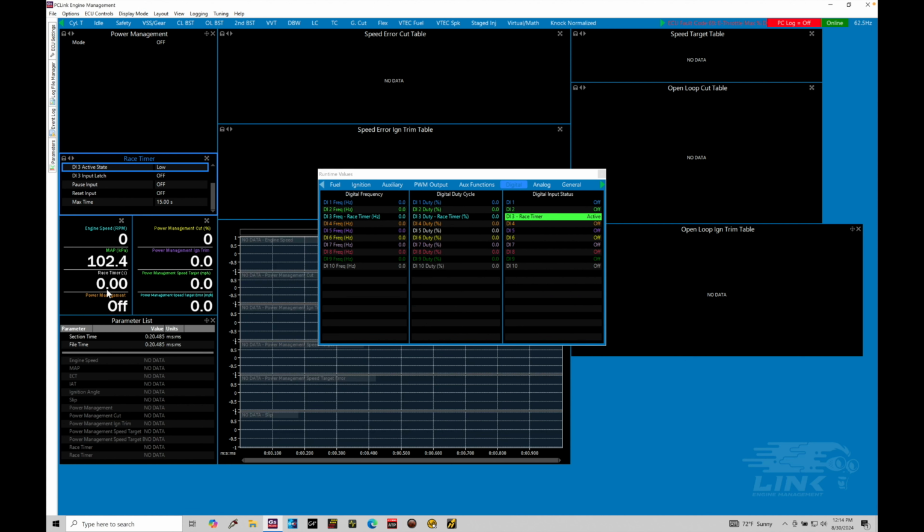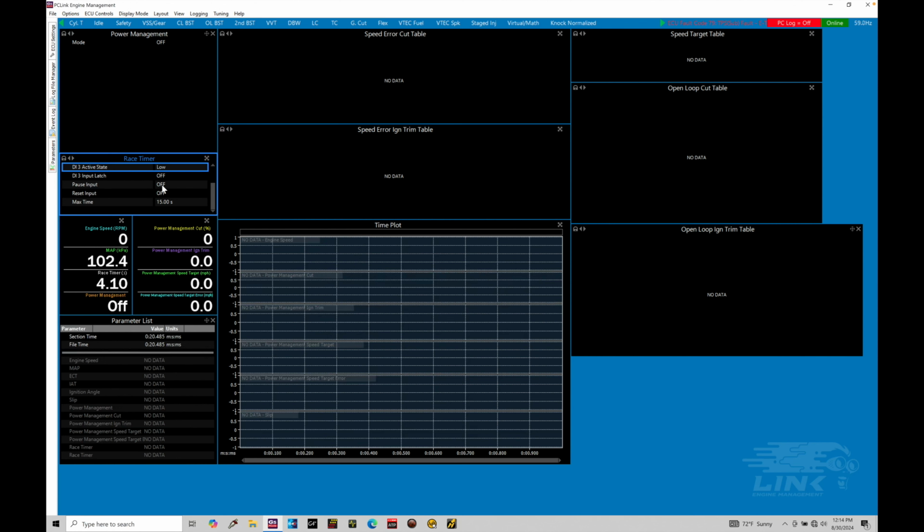At any point in time, if I push the button, it's going to reset itself back to 0. That can be extremely problematic, and it may be something that could cost us a run if we accidentally hit the button. So definitely put the momentary button somewhere that you're not going to accidentally hit it. But we can see here, I let it go, it does that reset option. Pretty simple. So I push it, it resets, let it go, it starts the count up. Okay, let's go ahead and close our runtime value window.